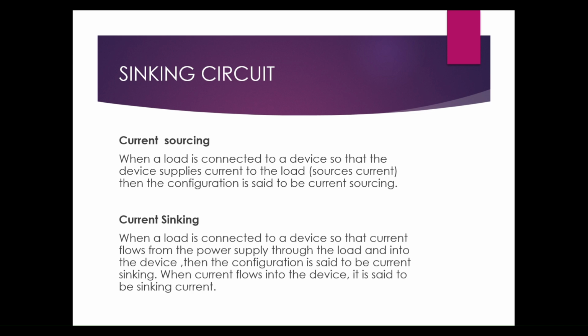Current sinking: when a load is connected to a device so that the current flows from the power supply through the load and into the device, the configuration is said to be current sinking.